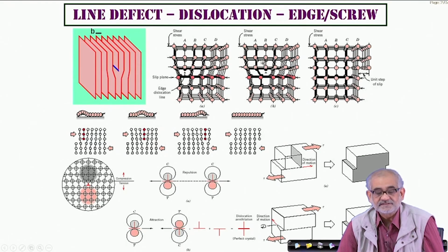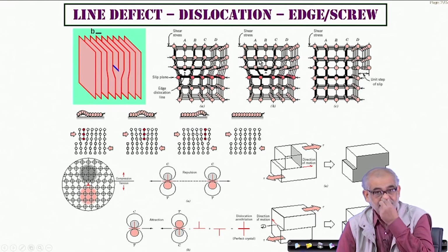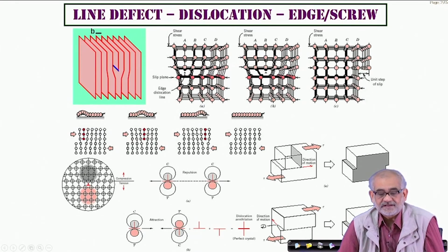So that means there is a closure failure, and the closure failure, dimension-wise and direction-wise, defines a particular characteristic feature called the Burgers vector, which defines exactly the existence and the dimension of a so-called edge dislocation. So whenever you have such an extra half plane introduced inside the crystal, this blue line here defines the end of this extra half plane.